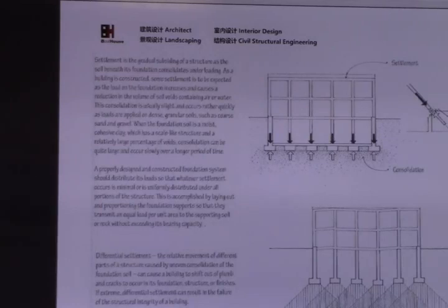This is our foundation to transfer the load. After the loading is applied to the structure, the structure transfers the load to the foundation and to the soil. A very important thing is the foundation can settle. Settlement means they get deeper and deeper because they have the load.